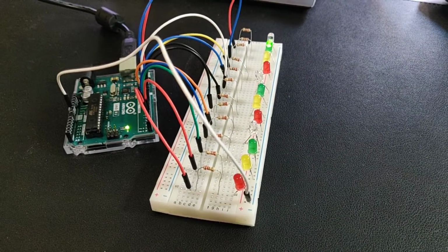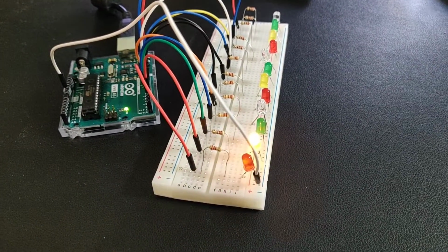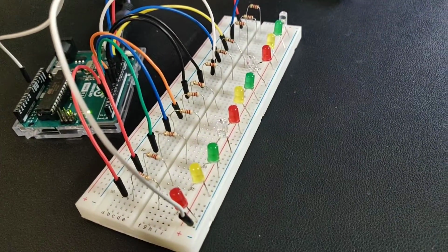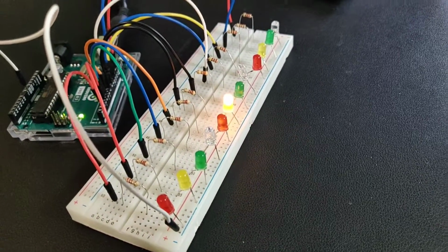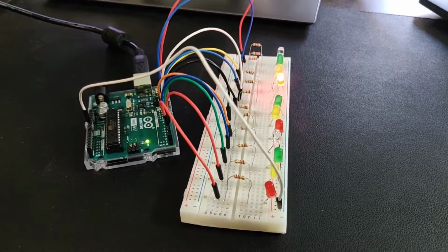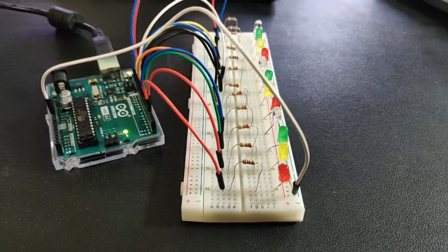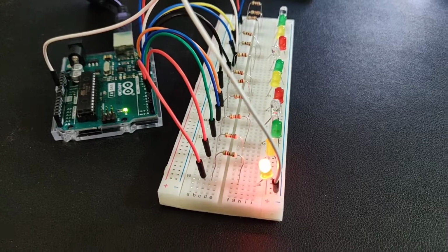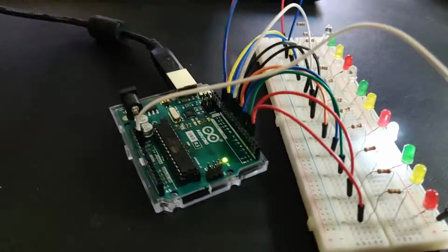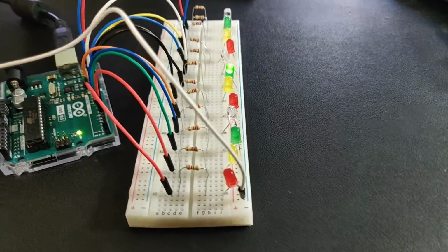This is the result of the second logic of code that we're running at the moment. It's the blink one LED at a time logic. So notice how just one LED blinks, turns off, then the next one, then the next one, and the next one. The only difference is the code. The circuit is exactly the same. We're just telling the Arduino when we want to send voltage from each one of those pins and in what order. So that's why it looks like one at a time.